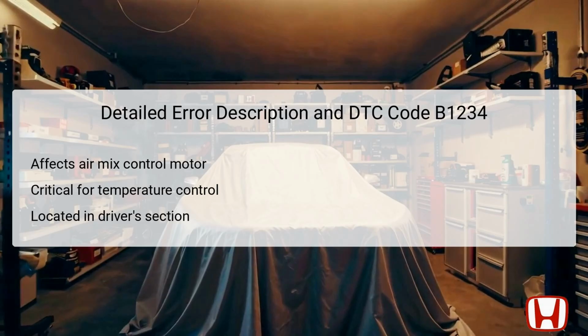It's important to troubleshoot not only the motor itself, but also the circuits connected to it to isolate the root cause effectively. Several factors may contribute to the occurrence of DTC B1234. The primary suspect is a short circuit affecting the air mix control motor circuit, which can disrupt normal operations.